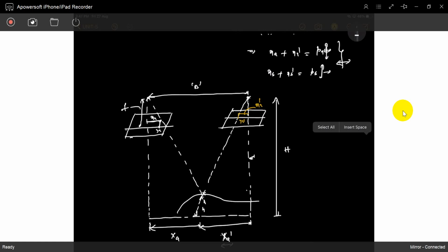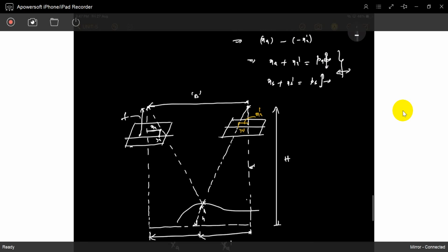Air base, you can call it as an air base. Okay, this is air base. So for one photograph, how much is the effective area? When we take two photographs, the distance on the ground in between the two photographs is called air base. Are you understood?